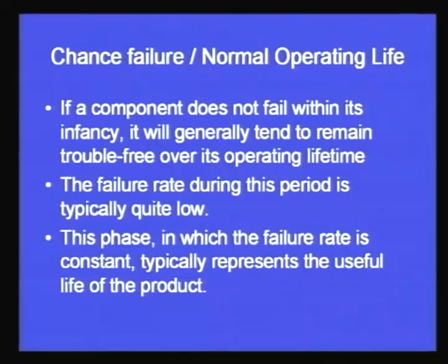So, till now we have discussed the basic aspects that are an integral part of infancy or the burn-in period. Now, coming on to the second stage, that is the chance failure or the normal operating life failure. If a component does not fail within its infancy, that is the first phase of the bathtub curve, it will generally tend to remain trouble free over its operating lifetime.